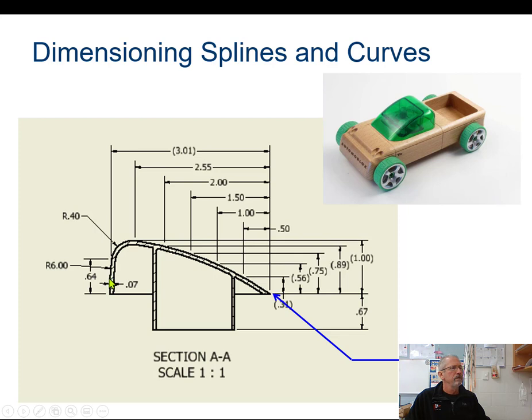And you can see, here's your section lines in here that go in there. This is a very bad datum. I disagree 100% with this. Datums should not start out with an edge like this. If this area here is straight, this should be your datum line. That absolutely should not happen, Anthony. So Anthony's got to get his act together here.